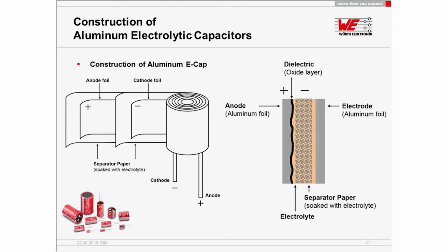And due to this, gassing would also happen, and this is a case where traditional aluminum electrolytics can explode, and why you normally find a vent on top of the product, to avoid the capacitor exploding in an undefined direction, so that you have a predefined direction where the gassing can reduce the pressure again.